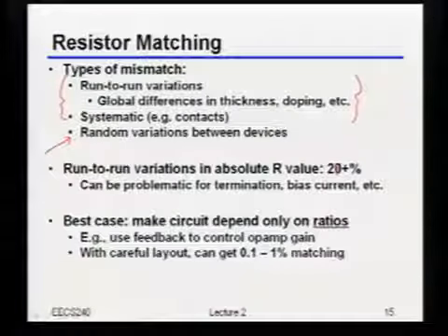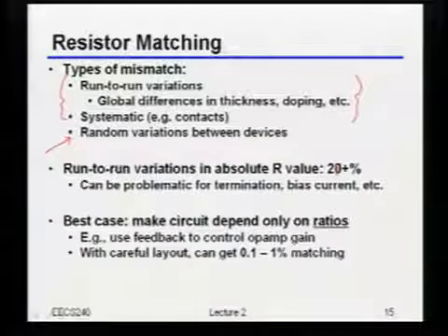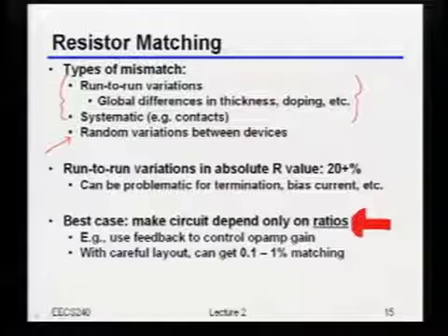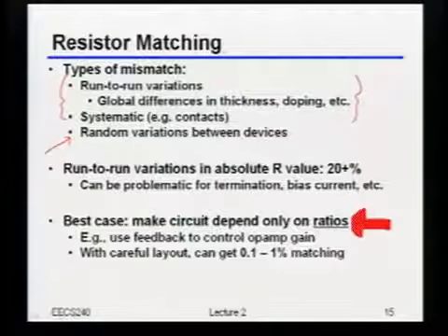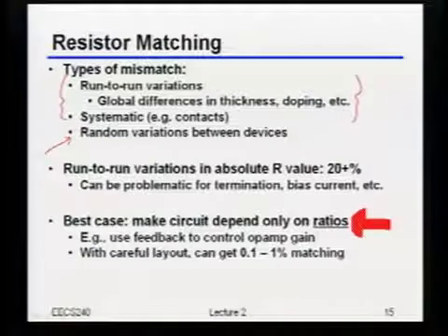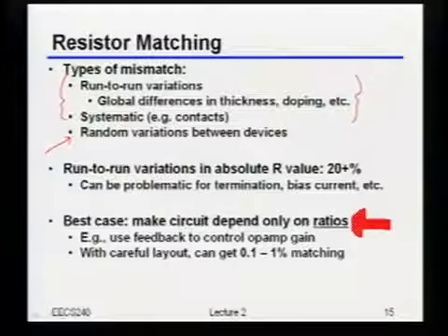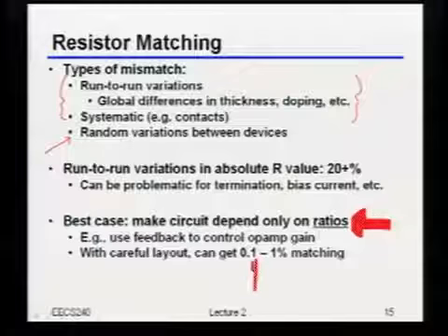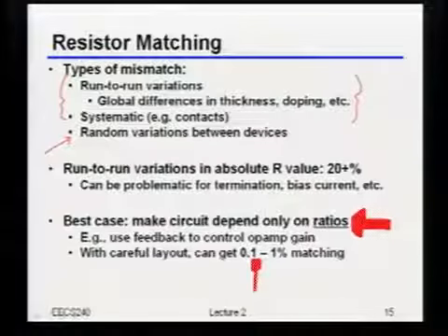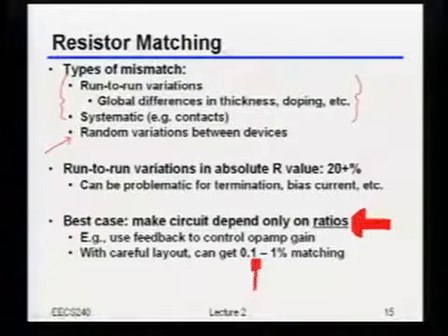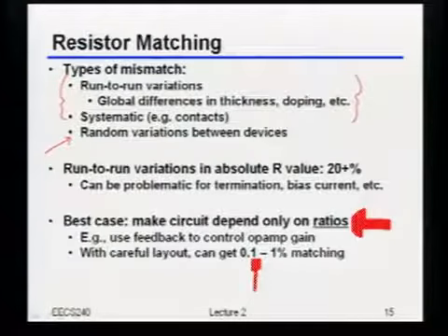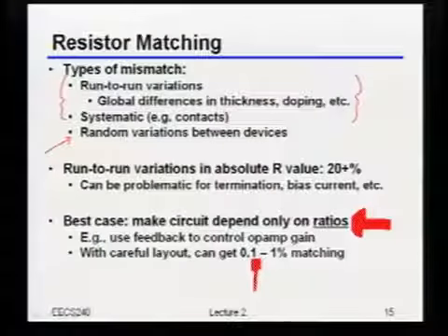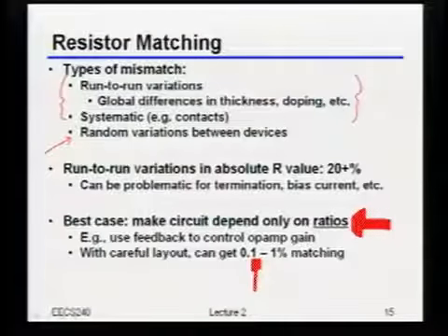So that's why, again, if you really look at analog circuits, and in particular why CMOS circuits have actually eventually been successful, it's because people figured out how to make sure that they made their circuits only depend on ratios of otherwise identical things. Okay? Because if you make it based on ratios, you can do extremely well with CMOS. Okay, and I gave some numbers here, anywhere from let's say 0.1 to 1% matching. In fact, you can even do better than that. Okay, so just to give you some idea, that's about 10, 12, 13 bits kind of resolution that you can get just based on doing that kind of matching.